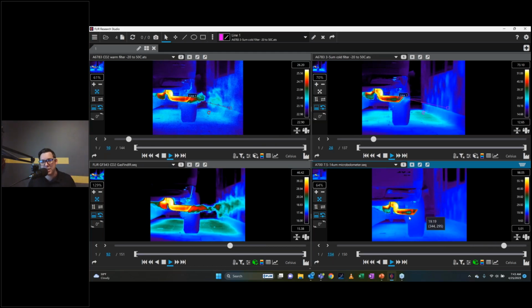Now, there are other gases where we have actually taken the core of what's in the A700, put that in a handheld, and done a lot of digital image processing and some additional filtering in the lens to build a portable camera. I believe it's for methane, the GF77 model camera. That is the only bolometer that I'm aware of that anybody really has to target that kind of range, because it is so difficult to leverage those detectors for that. But that gas specifically has something that can be exploited in that 7.5 to 14 range, and that's what's important.